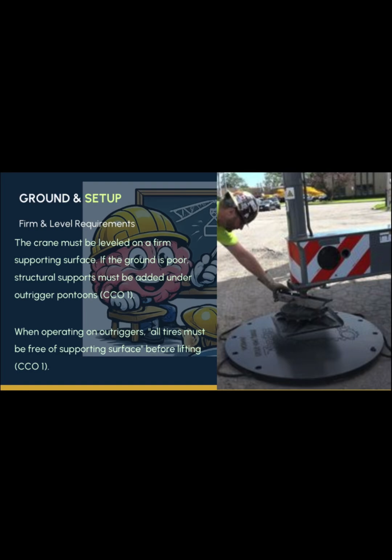Unlisted angle. When calculating fly capacities for angles, not just fly, for calculating boom angles, when the angles are not shown, we go to the next lower radius. We always err towards lower capacity. And remember, as we lower boom angle, we're shifting the load farther out, which is going to decrease our capacities. Always go to the next lower allowable boom angle. We also call that the loaded boom angle.